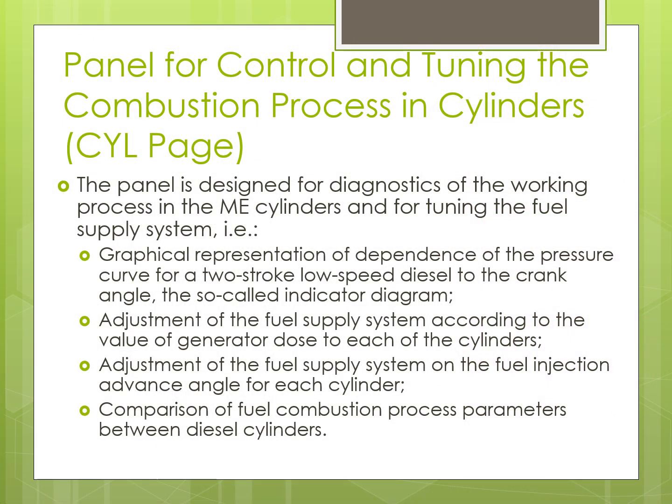Panel for control and tuning the combustion process in cylinders. The panel is designed for diagnostics of the working process in the ME cylinders and for tuning the fuel supply system. Graphical representation of dependence of the pressure curve for a two-stroke low-speed diesel to the crank angle, the so-called indicator diagram.